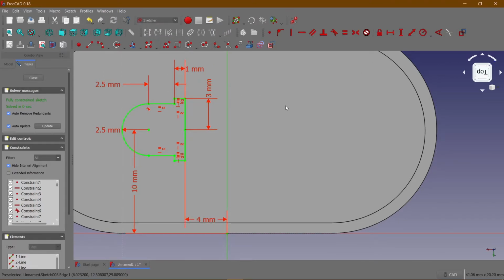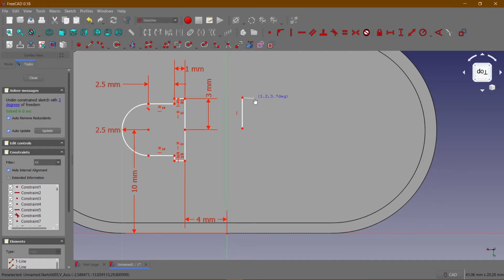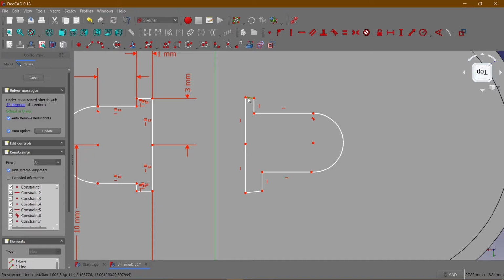So I'm going to create a mirror image of this on the other side. We already know how we did the other one, so I'm going to perform the same thing once again. So this is polyline 2. I'm going to change the behavior until it turns to an arc, then back to a line, until it changes to yellow. So there's a coincident at that point. So I'm going to give a vertical constraint here, a vertical constraint here, a vertical constraint. To zoom in, you can just use the mouse scroll wheel to zoom in and out, and that is it.